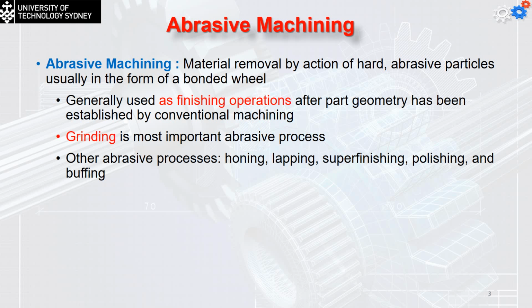Then we had the deformation of the material. We said we can take the material, we can forge it, we can roll it, we can punch it, okay, to make a new shape. And once again we said this was not enough to finalize the product. So we talked once again about cutting machining, how to use drilling, milling, and turning to cut off part of the material in chip form to reshape the material into a new shape which is going to be similar to the designed part.